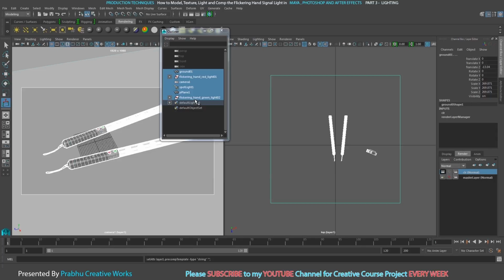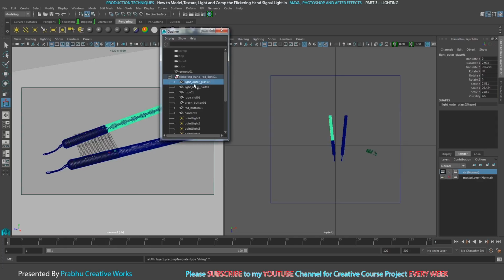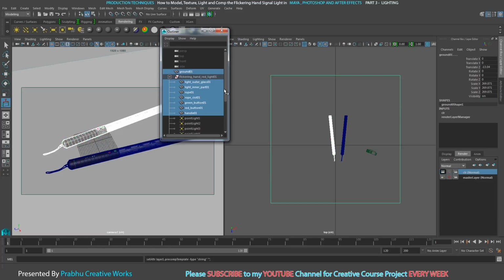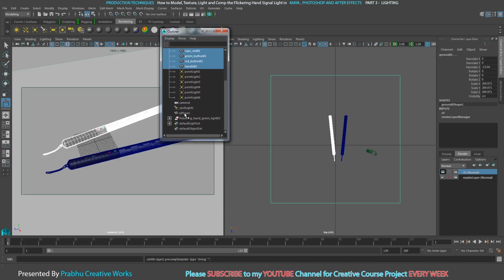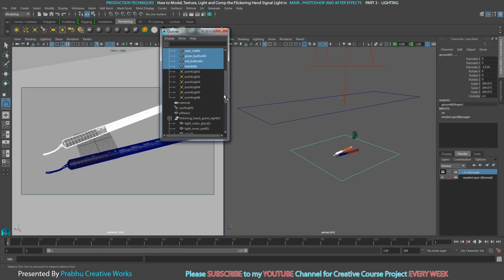Now I want to add only the models. So go inside our group, select all the meshes in your scene using the control button. Don't select the point light. So I will select this one, using control, and choose the ground also and expand this. Don't select this reflected surface. So I will go to perspective. So don't select this reflected surface. So, occlusion pass. So now I want to expand this group.